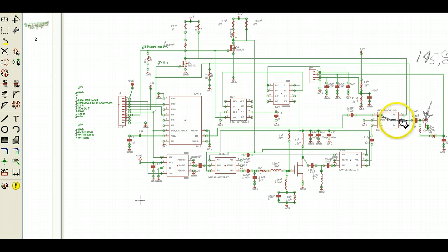It's controlled via logic from the push-to-talk signal. When the push-to-talk signal is low, this switch is in this position, and the RF signal proceeds through this switch, through this DC blocking capacitor, and into the receiver module. This receiver receives this signal and puts out a couple of signals.